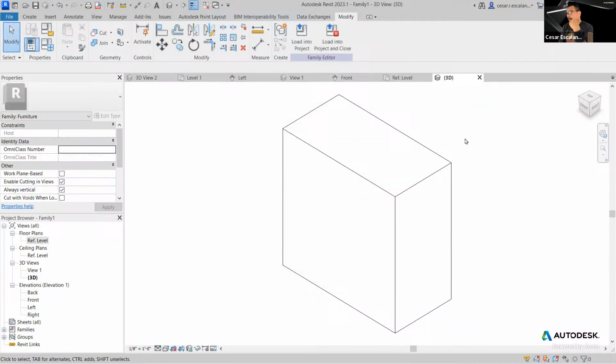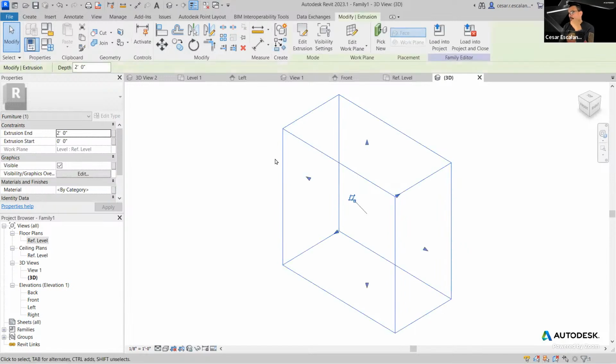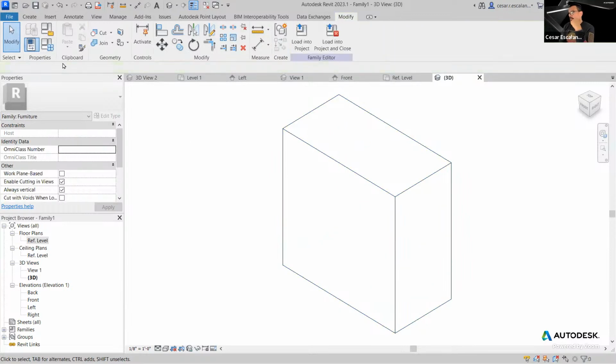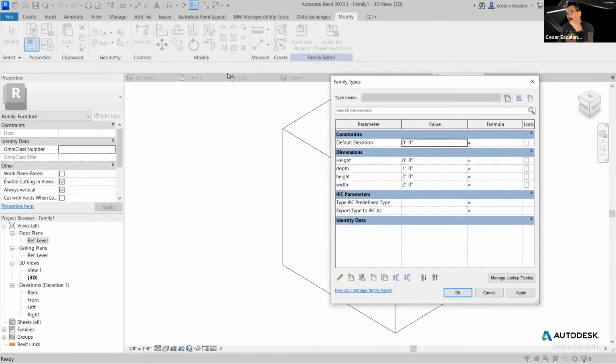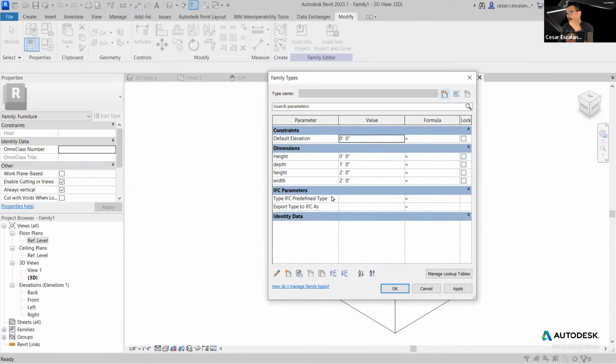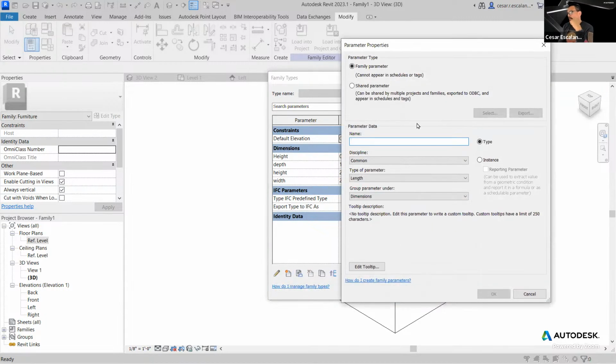And then, now that it's part of the furniture category, you can also assign materials or create custom materials. To be able to associate materials from the project, you build a material parameter inside the family editor. So here, I'm going to add a new parameter. And this one is going to be called table material. And we're going to make it an instance. And what that means is that the user has the ability to select a different material by instance. And the type of parameter is material.